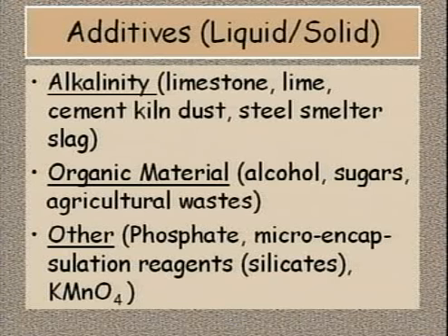Before you commit to using this approach, consider the volume of mine waste that needs treatment and the physical situation at the site. Additives might not be practical if the mine waste facility measures in the millions and millions of tons in size. Injection of liquid additives may require good hydrogeologic or hydrologic control of the solutions. In general, these approaches need to dovetail with other ARD control measures to be successful over the long term.